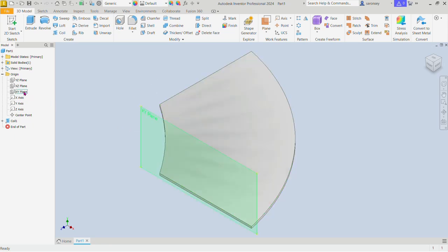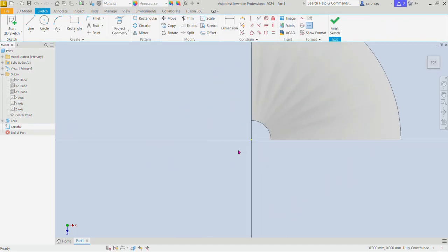For that, we have to pick a plane to work on. Let's see, we can work on the XZ plane. And so I'll click on that and then choose the option here that says create a sketch. The sketch is going to be a circle, and so I'll pick the circle command up here. Bring that to the origin. Just draw a circle and specify the diameter of this circle with the dynamic input box highlighted in blue, just type in 30 and press enter.